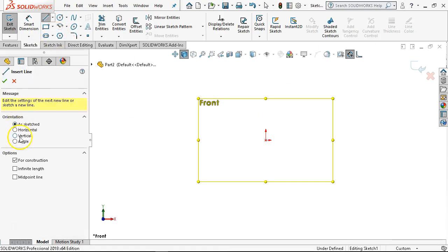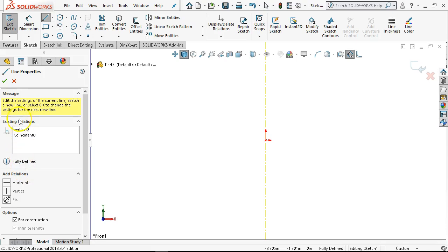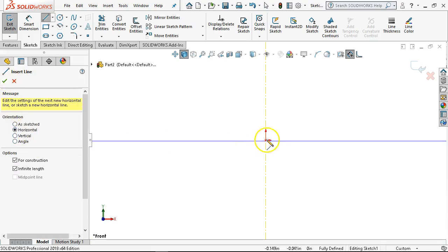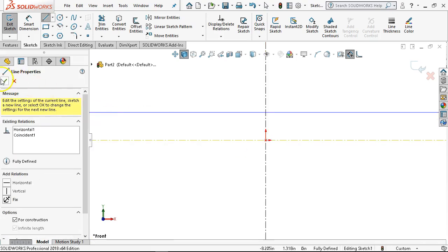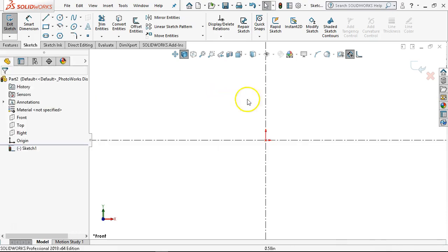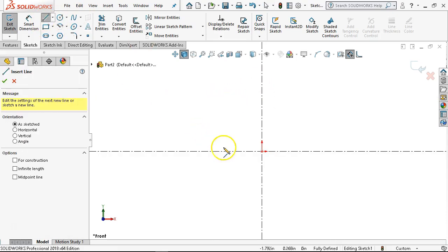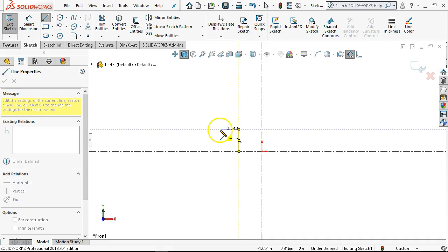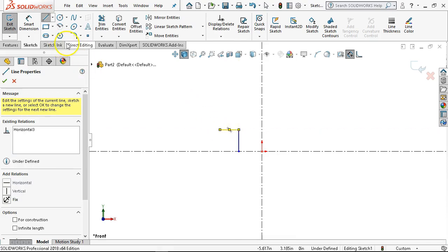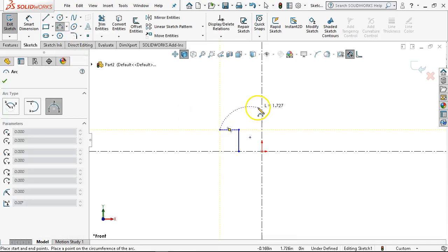All right, so symmetry says center lines, horizontal or vertical, to start with. Put those in place. And then one side will get line, line, and arc. Since it's a partial arc, well, we could go with the, it's 1.75 in diameter. Now that's not fun. Let's go with the 3-point arc, and we'll draw a partial.